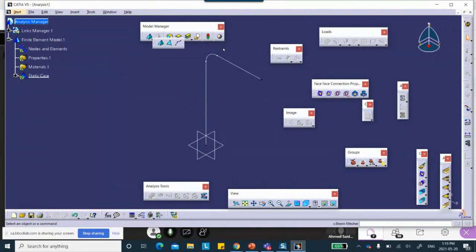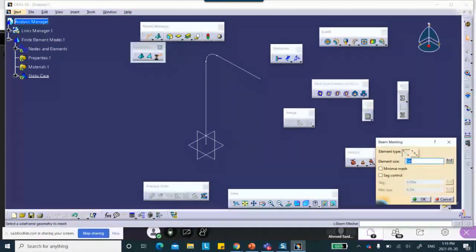So in this toolbar where the traffic light is, Model Manager, this is the three-dimensional object, three-dimensional element. This is the beam element. In between, we're going to come and do it next week. These are called shell element, pop can, propane tank, the hull of a ship and things like that. You do it with this. It's a beam element. That's what beam mesher does.